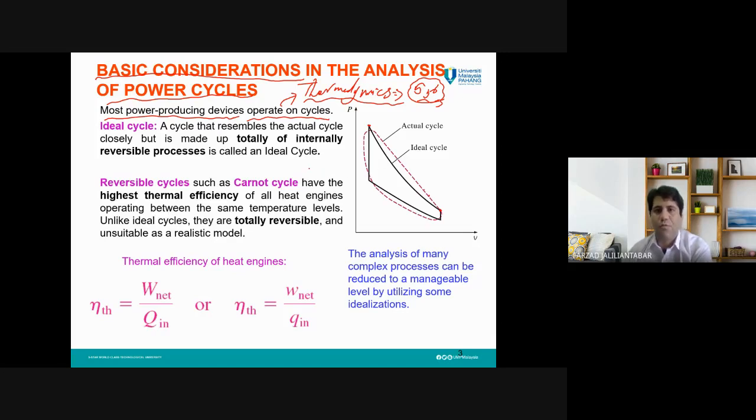If you remember, for example, for this one, because it is a simple one, I start with this. This is a constant volume process because you can see this is almost a vertical line. So the volume is constant during this process. So if we know how much is the pressure here and here, we can draw this because we know also it is a constant pressure process. But this is just an assumption. If you remember, for a constant pressure process, we need to have frictionless devices, for example.